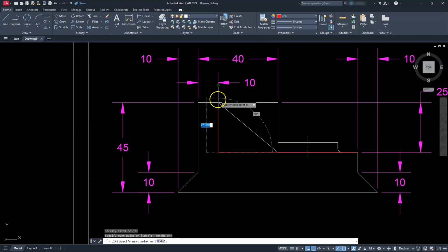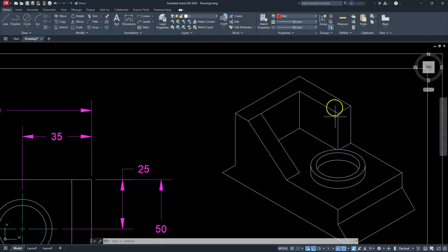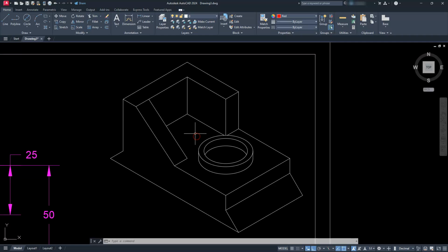If I create this portion here, then that's a good 70 percent of it. So if I create that portion first, and then I'll create this block here, and this block, I'm left with this kind of donut shape here at the front. Once I put all of those together, it should be simple enough. So looking at it, I can see 4 distinct shapes that I can use in order to create my isometric.